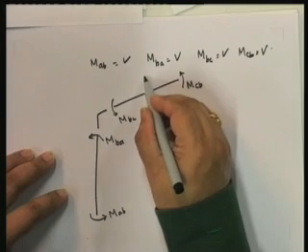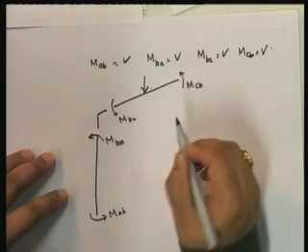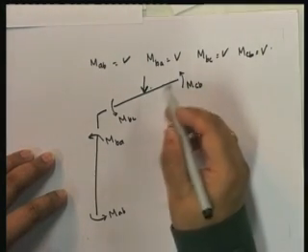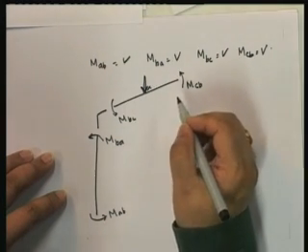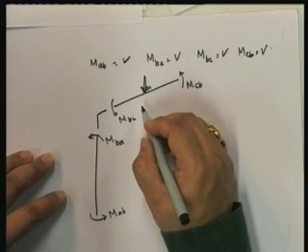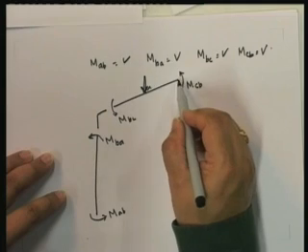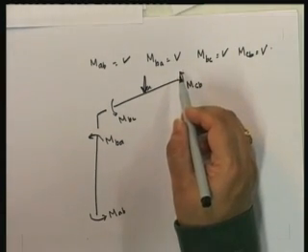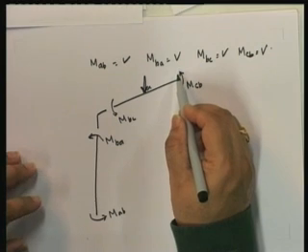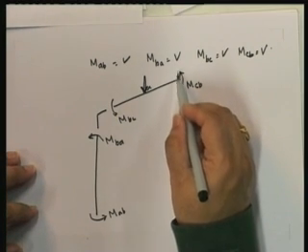Okay? Note that over here, what do you have? You have this load, okay? And over here, what are the things that you have? Note that at this point, I know that there is not going to be any vertical reaction. Why is that? Because it's a roller.